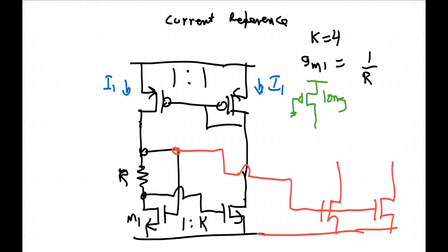So it kind of acts like a resistor, and then you look at this voltage here. Okay, so if the voltage on this transistor here is at ground, so it's not started up, then the PMOS up here is going to pull this node up to the power supply. And if this turns on, then you want this node here to be pulled all the way down to ground. So this has to be a very weak and long transistor.